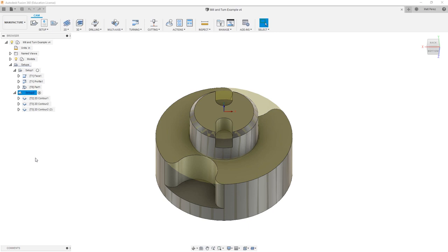Because we are removing this part from stock, when we create an STL file, it'll actually leave both pieces of stock in the file. So this can be problematic, and it does include it as a single body. So when we're trying to use that for things like rest machining, again, it can be problematic. Another thing to note is the potential difference in scale when we export that STL. So you will likely have to scale the file down, especially if you're working within the inch unit system.